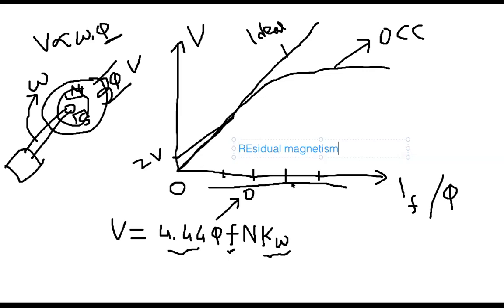And then of course you need to excite the field or apply the field current, then gradually voltage will build up. So I'm talking about this initial one. This amount is called the residual voltage due to residual magnetism or remaining magnetism.